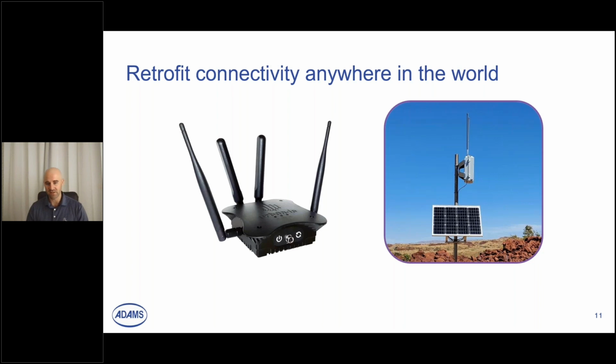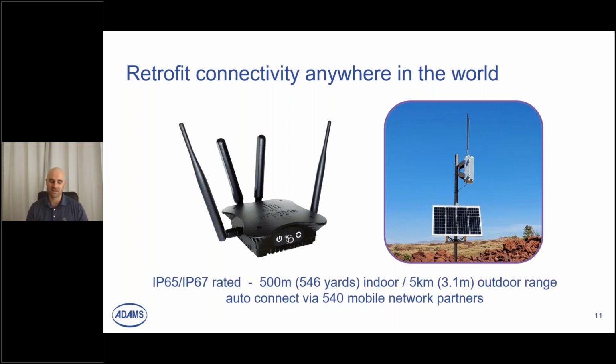So we can collect all of this data from the range of sensors. And the big differentiator on this gateway technology is the sensing range you get. So unlike Wi-Fi and Bluetooth that have a mesh network or a multitude of different gateways dispersed at a facility to get enough coverage, this is a solution that gives you 500-meter indoor range or up to 3.12-mile outdoor range in a radius, so you can deploy fewer gateways to connect to more devices across a large campus, for example.